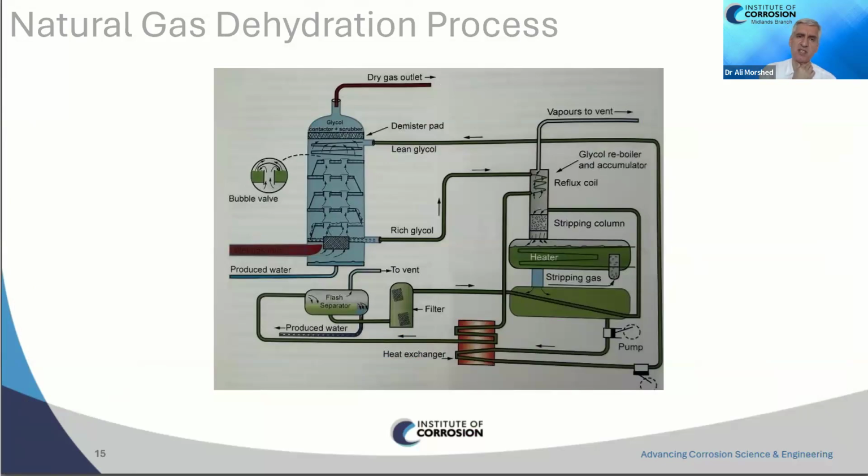Going back to the dehydration process, on this slide you see the dehydration process in a typical gas refinery, where the lean glycol enters the contactor tower here, and it contacts the wet gas which is entering the tower from the bottom.